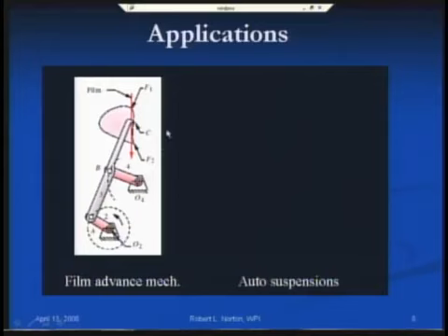So to accomplish that illusion, the film projector, and for that matter the camera, must expose the film, in the case of the projector, to the light that's going to put it on the screen for a brief moment. I think a 60th of a second is typical, and then close the shutter so the screen goes black, move the film to the next picture, and then open up the shutter and let it go light again so you see the new picture. This mechanism is what moves the film from one position to the other. So the film is moving, stopping, moving, stopping, moving, stopping 24 times a second.